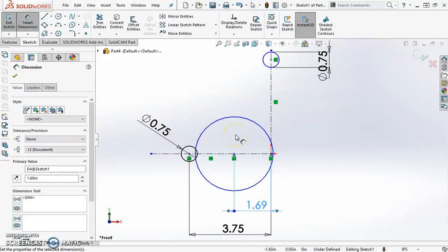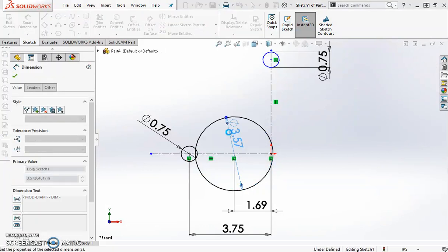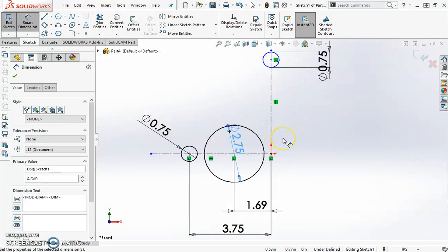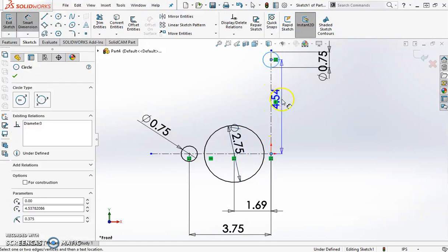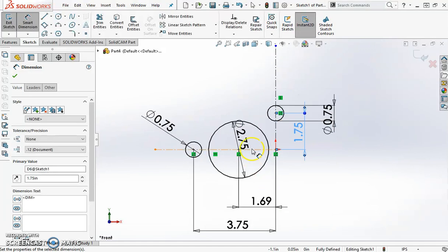And I noticed here that I never adjusted the size of my big circle, or never dimensioned that. So you can go ahead and dimension that, and that big circle actually has a measurement of 2.75. Okay. So this is the distance away from the origin for both of these. It needs a distance away for this top one. And if we go from our origin all the way up to that circle, you can see there in the picture on the far left side, it says 3.5 divided by 2 is what we need. Okay. So that kind of placed this.